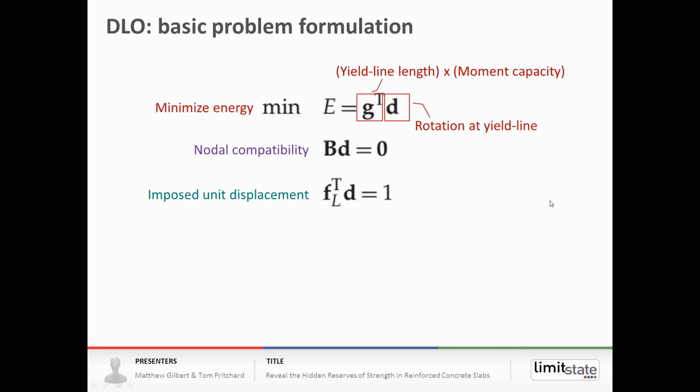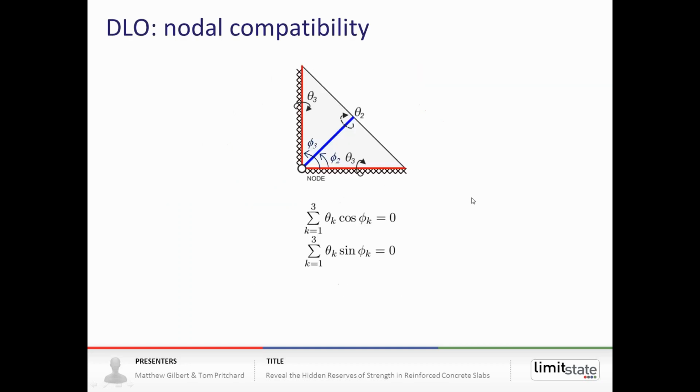In terms of equations, what we're basically doing is minimizing energy subject to nodal compatibility constraints, and also a unit displacement constraint, taking advantage of the theorem of virtual work. It boils down to a simple linear optimization problem.